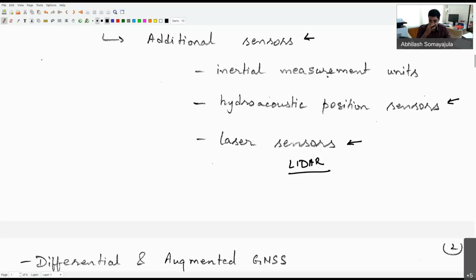It measures based on the intensity. How much is the intensity of the light deteriorating? Because as the light propagates through the medium, there will be some scattering. So based on how much got scattered away, it makes an estimate of the distance. So LiDAR is not just using time of flight. Time of flight will be very difficult for very short distances. It's using the intensity measurements in order to characterize how far the light has actually traveled.